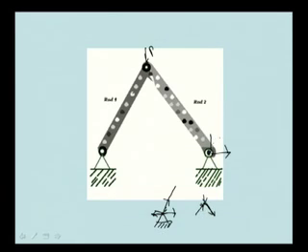So actually you have 3 pins. You can resolve the components of the forces in two directions, and you can get two equations for each pin: sigma Fx equal to 0 and sigma Fy equal to 0.